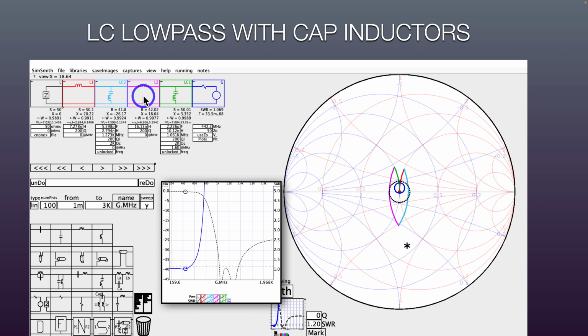And then on top of that, I can take the capacitors that I put into here and note the values of the caps, then replace them with an LC with this L in the shunt leg to then add in a couple of resonance higher frequency traps down here.